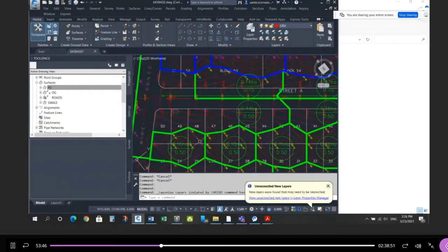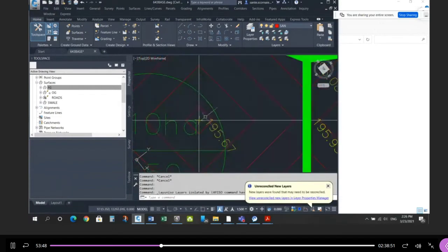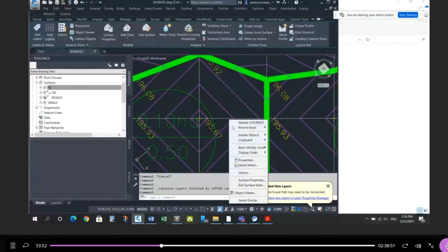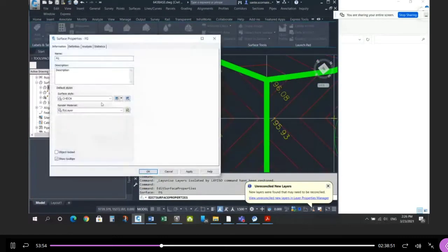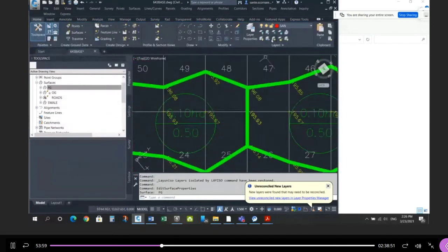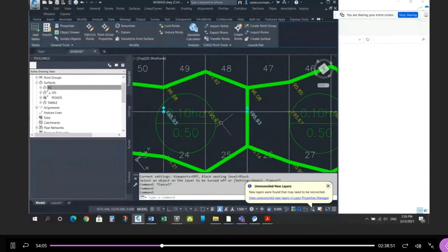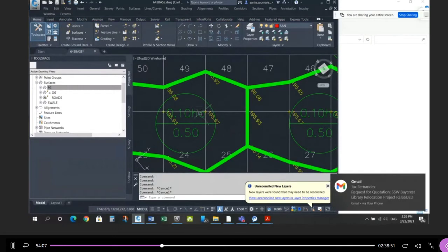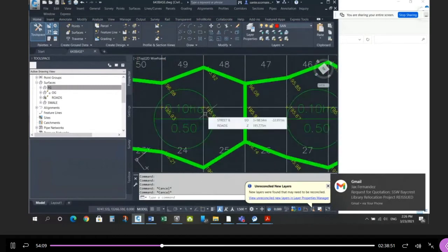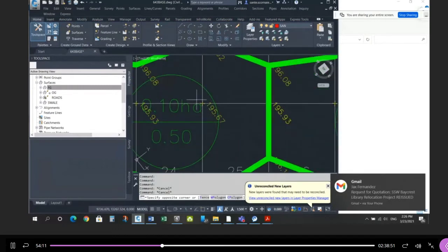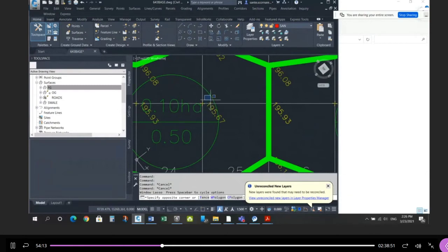Let's take a look. For the rear lot catch basin, you can see this is the low point, with all the contours converging. Let me turn off the drainage areas for a second. You can see the low point, right? This is 593, this is 593, this is 567. So this corner is the low point. Now where does the catch basin go? Well, you have four options. It's either in this corner, in this corner, in this corner, or in this corner.